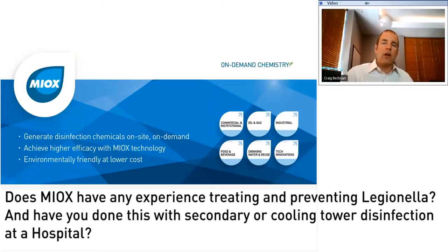And the reason often is that they're trying to prevent that biofilm buildup. And what the industry and users have found is that if they change the biocide chemistry, they can actually prevent some of that biofilm growth where the Legionella perhaps is embedded so that it can't get in contact with the chlorine. The MIOX chemistry does the same thing, but with less cost and more easily, because we can remove and control biofilm without multiple chemistries. We wouldn't need a mixture of chlorine and bromine with a periodic surge of isothiazolone, for example.